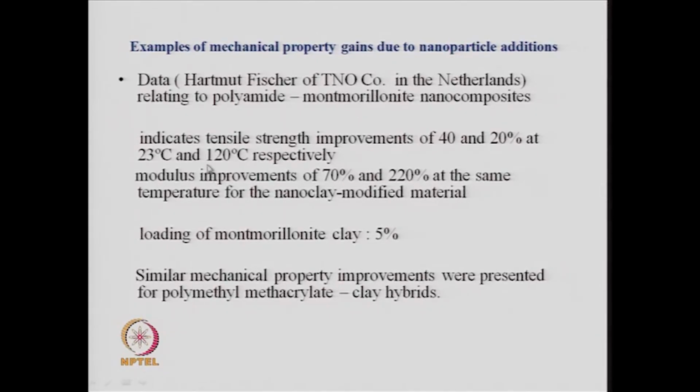So, this report of this company showed that the tensile strength improves nearly by 40% at nearly room temperature, and if you increase the temperature to say 120 degrees Celsius, then the improvement is still there. However, it goes down from what it was at room temperature. So, from 40% at room temperature it becomes 20% at 120 degrees Celsius, but still it is much higher tensile strength than the polyamide by itself if you do not add this clay